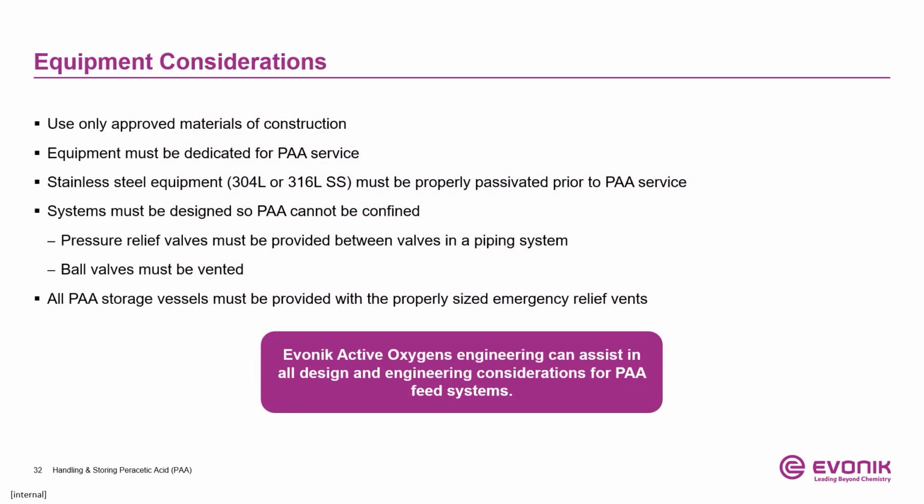Next, let's turn to the equipment considerations for peracetic acid. You must use only approved materials of construction with PAA solutions, and the equipment must be dedicated for PAA service. All stainless steel equipment, 304L or 316L stainless steel, must be properly passivated prior to PAA service.